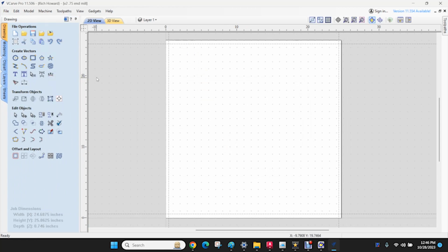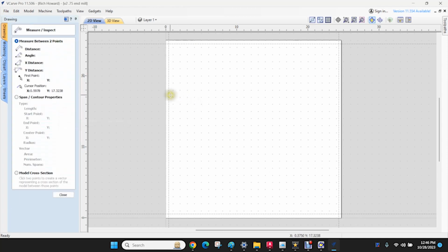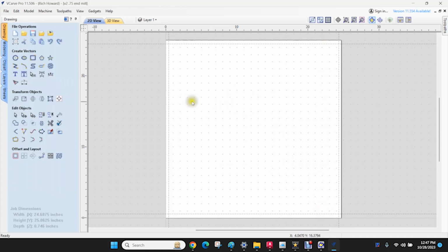So we know the OD, the overall width and length, so to speak, is 23 13/16 minus 1/8 of an inch over here because of how that bit's going to come through. Over here, same scenario. Should be 23 15/16. And it is. Okay, so this is good.